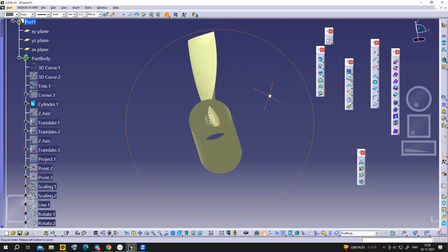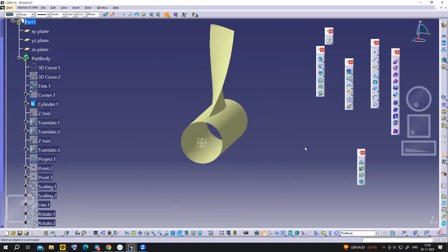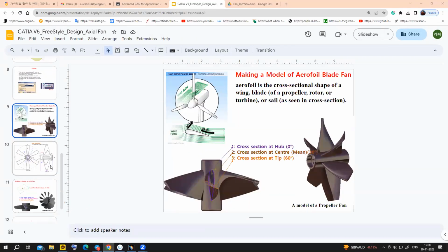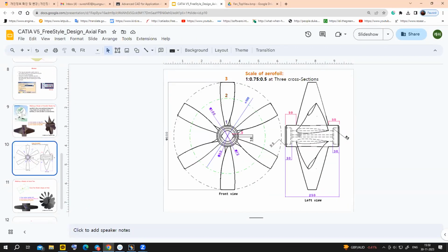Okay. Yeah. So now what I do, we fill this one, close the surface, right? For that one, I'm going to use part design because I can use generative shape design close surface, but I want to make minor changes here, right? Create a hole, okay?